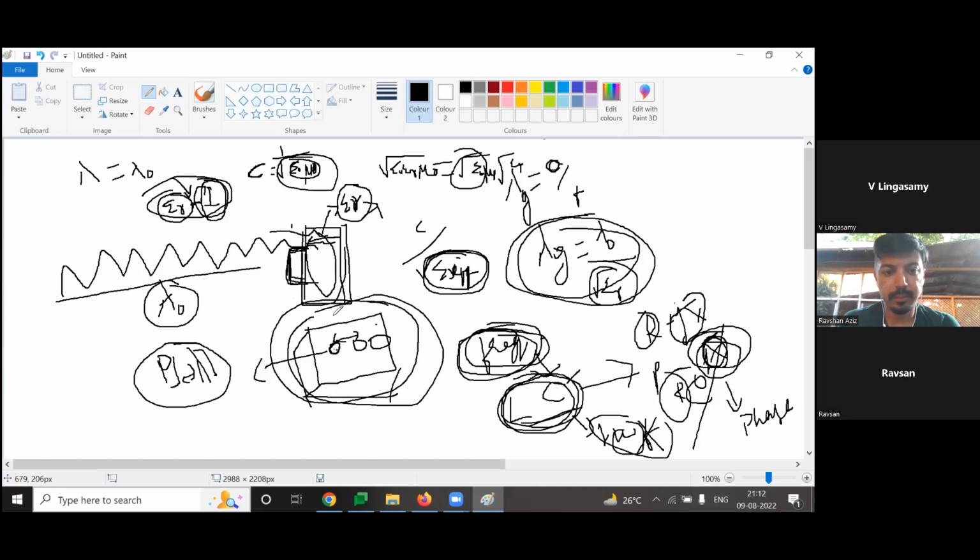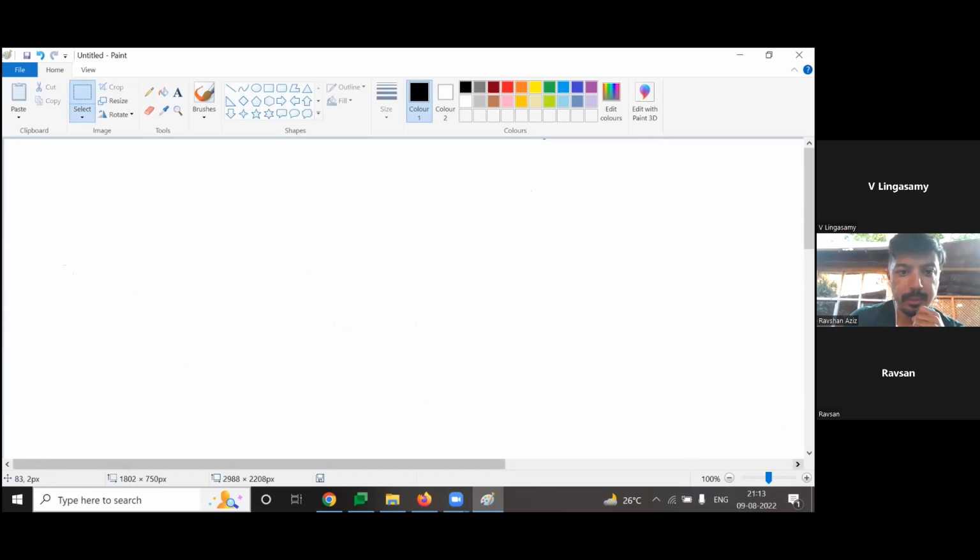But if you look at this overall perspective, you do not have a uniform dielectric, right? There is a metallic patch over here. This will create some kind of offset, for example, the effective dielectric constant gets changed. Therefore, when the dielectric constant changes, frequency changes, L and C change, and phase will change. That's what is happening. Now, coming to your doubt, why are we using CST to measure that?